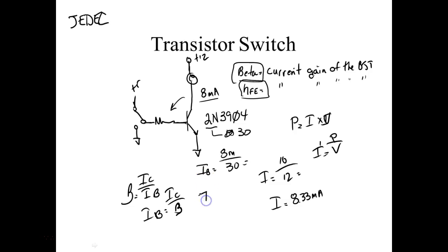Is that 266 micro? So what I'm doing is I'm able to use microamps to control milliamps, and that's the function of the transistor.